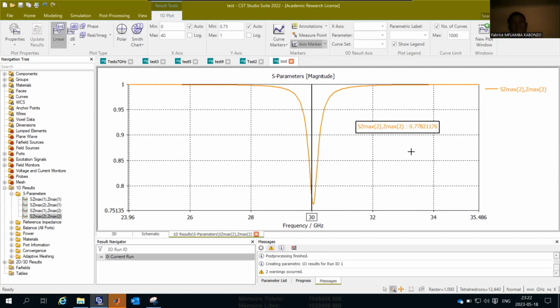What do you think about this? This is not a unit cell behavior. It's a substrate behavior, because your substrate size is the same, but at 30 gigahertz it is huge. For example, let's say 1 mm is almost 1 lambda, right? Yes. That also causes the losses, right?